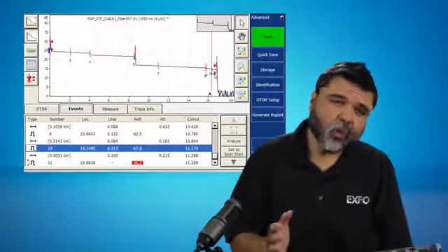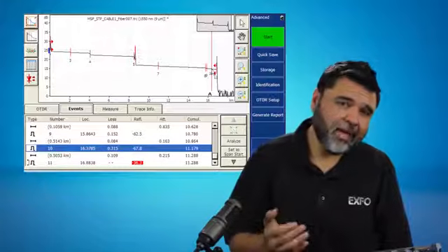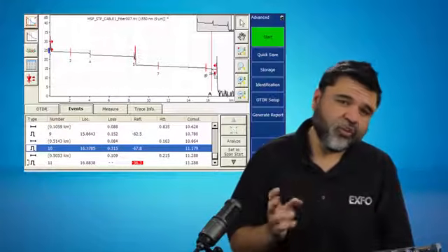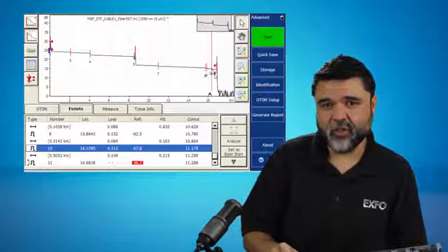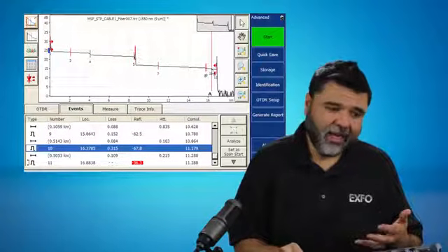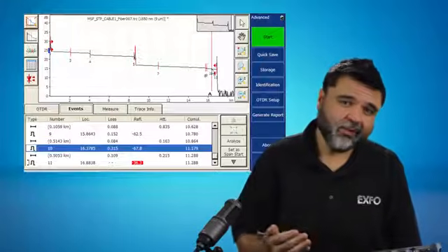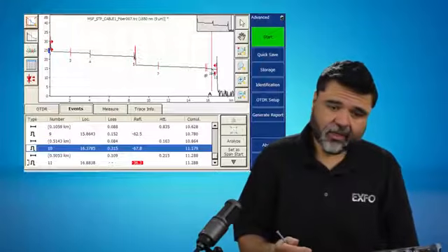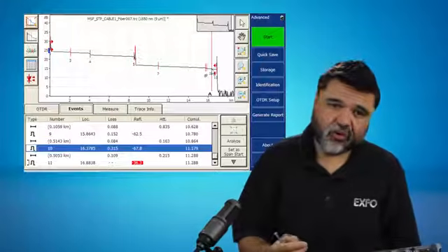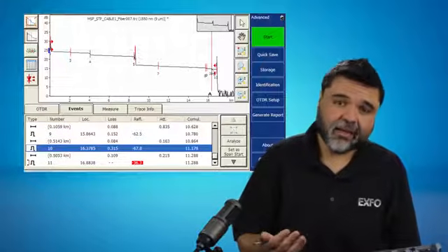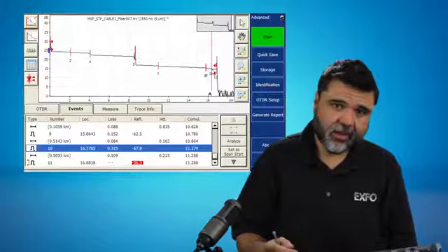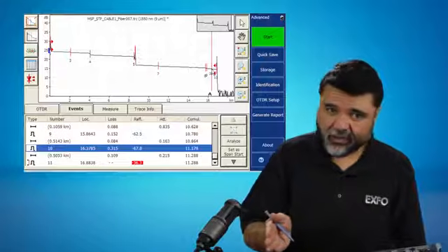And I have to tell you, most of the time that I spent maintaining a system was chasing dribbling errors because of a dirty connector somewhere. And if you're working in a large telecom hotel with a lot of customer handoffs, you might have a lot of tie cable connections. It's not unusual for some of these larger locations to have 8, 9, 10 connectors before they even leave the building. And so imagine chasing that trouble all day long.